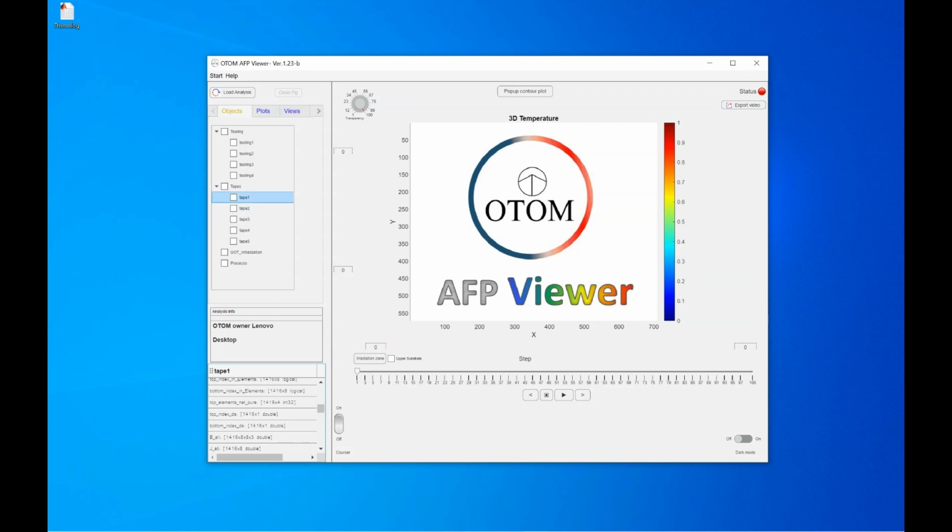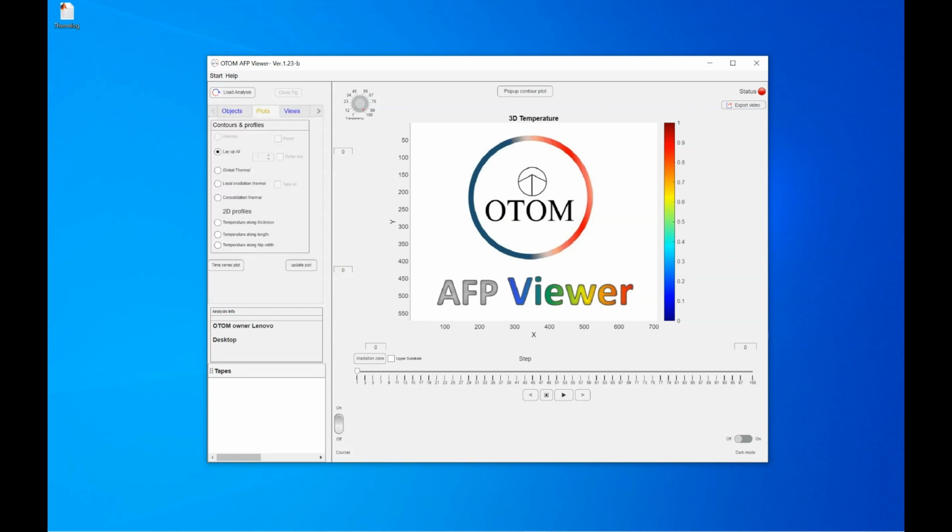So what we need to do is just select the object that we would like to represent. For example, all of the objects. Here, I select all of the objects, all of the toolings and tapes. And then we can go to the plots. The first one is the layup. So we click on it and click on Update Plots.